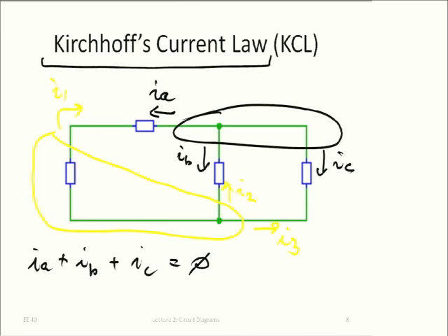Right? And so notice that I introduce names for currents just as well. The yellow ones and the black ones. So it doesn't matter that I introduce arrows that go in all sorts of different directions. I just have to be consistent, right? I cannot mix. I cannot say IA plus I2 plus I3 sum up to 0, well, because IA goes the other way. Or I1. Okay? As long as I'm consistent, I can introduce as many currents.